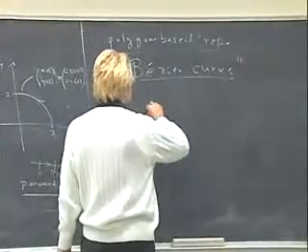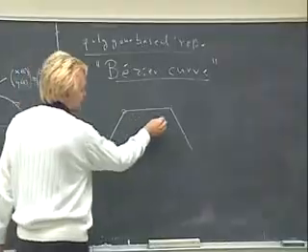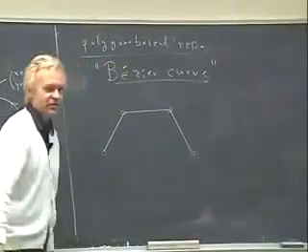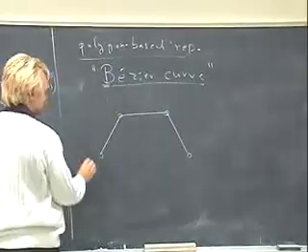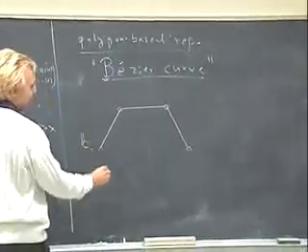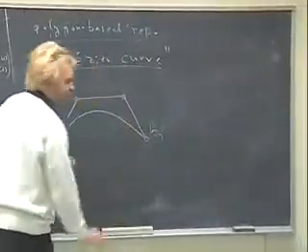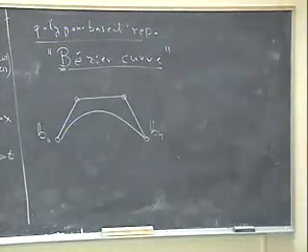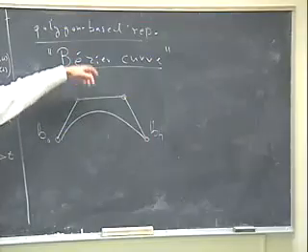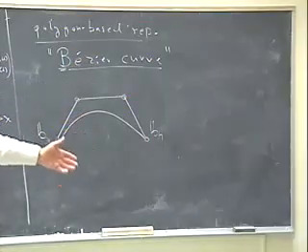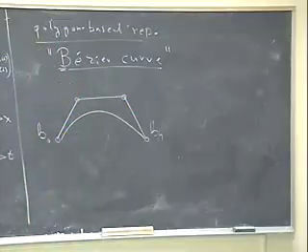So you sketch a polygon, you define a polygon. The polygon is defined by a bunch of points. These points are circles, and they are called B points, B after Bezier. So there is a first point, B naught, and then there is a last point, Bn, and a curve comes out. Okay, and so why is this good? When you take one of these points and you move them around, the curve will follow. Because the polygon defines a curve. So whenever you move a point, the curve will follow. That's very cool.